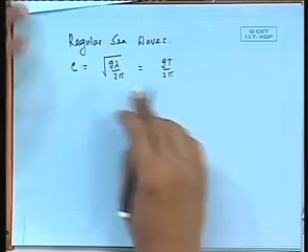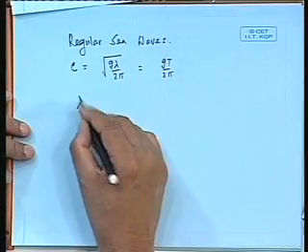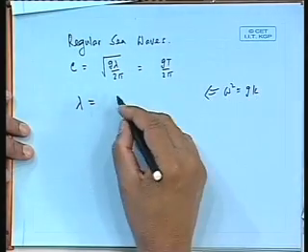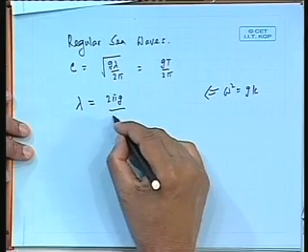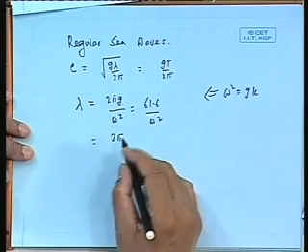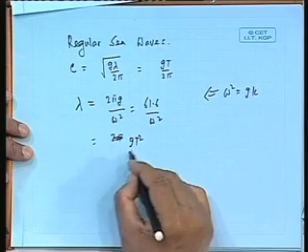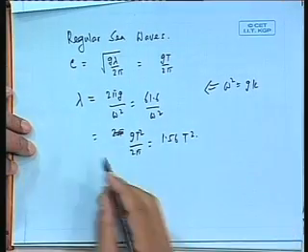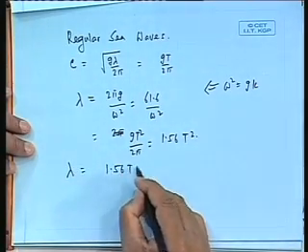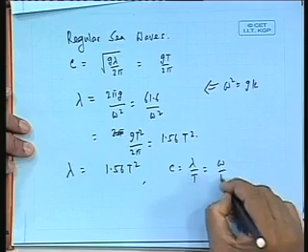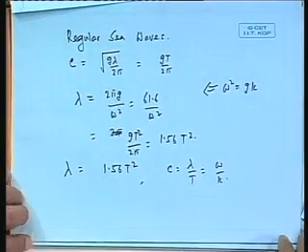In fact, we can relate lambda and T also from dispersion. From omega square equal to g k, working back we can find that lambda is equal to 2 pi by g into omega square, which is 61.6 by omega square. Or, sorry, it is g T square by 2 pi, equal to approximately 1.56 T square. So lambda becomes 1.56 T square, c equal to lambda by T equal to omega by k, etc. Why I am writing this is that let us try to find out some relation between speed, length, etc.